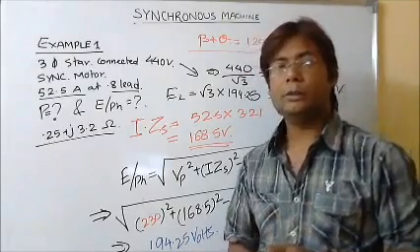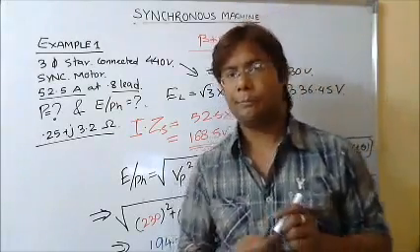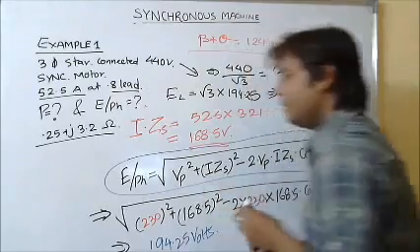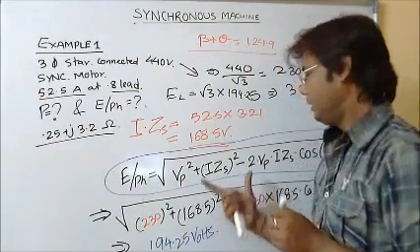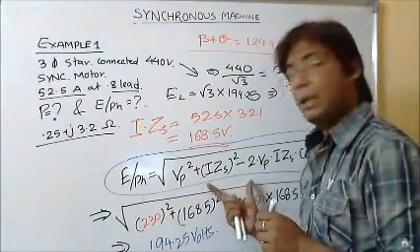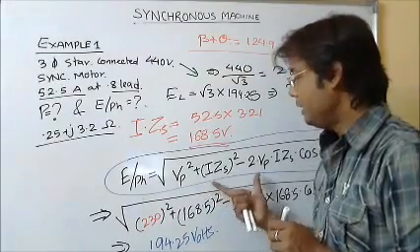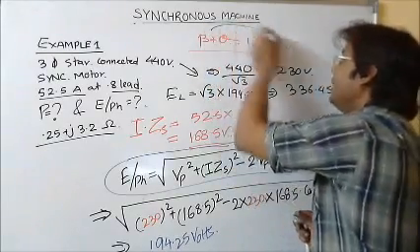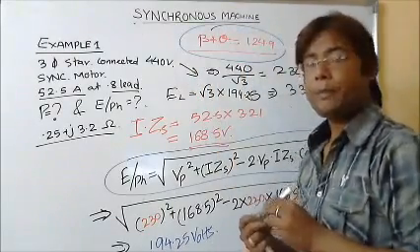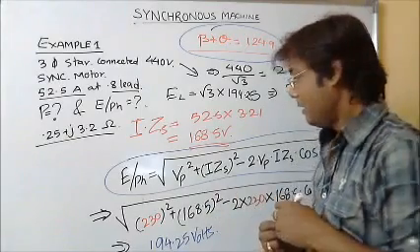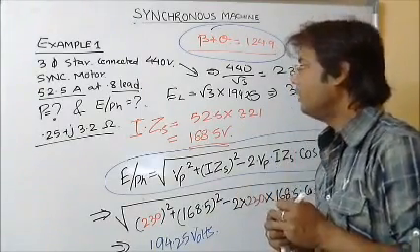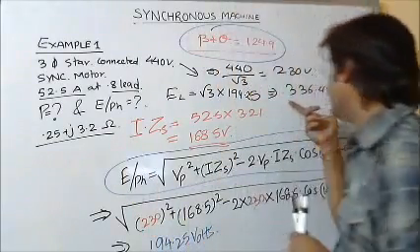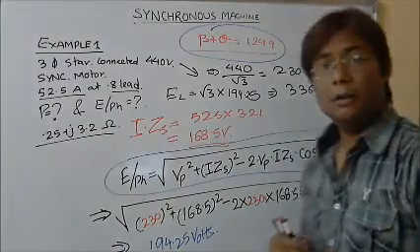So in this question, only two things were very important to understand. This was the universal formula which is normally used in any synchronous motor E per phase question. This is very important. Please remember this formula, learn it by heart. Normally such questions can be solved by this formula. Another thing is that when it is leading, it is beta plus theta. When it is lagging, it is beta minus theta. Apart from that, nothing is more complicated in this question. This is the answer, that is 336.4 volts.